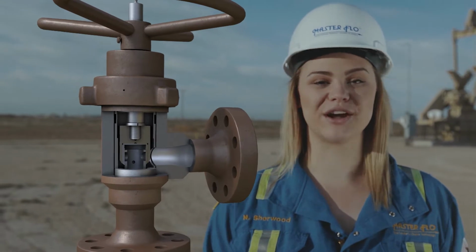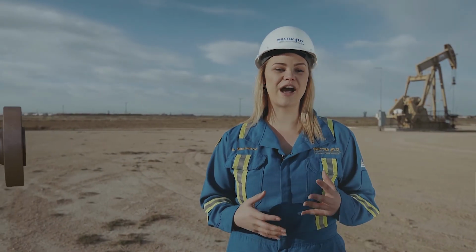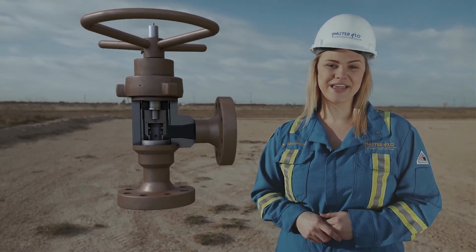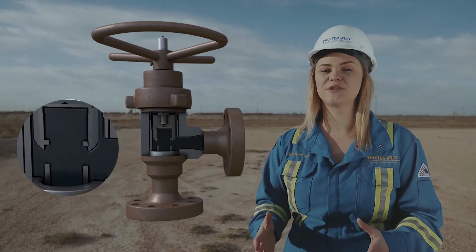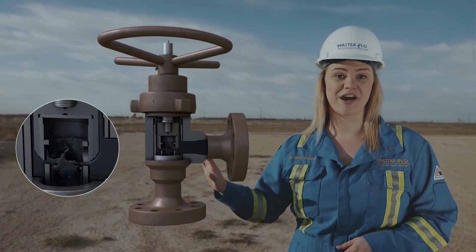This valve is best for high pressure drops and high sand concentration applications. Moving the seat to the outside where the fluid velocity is lower, reducing wear to the throttling surface and improving seat life. Reduction of valve outlet erosion is another important element of the external sleeve. It's achieved by directing the fluid exiting the throttling port into the valve trim and away from the valve outlet.